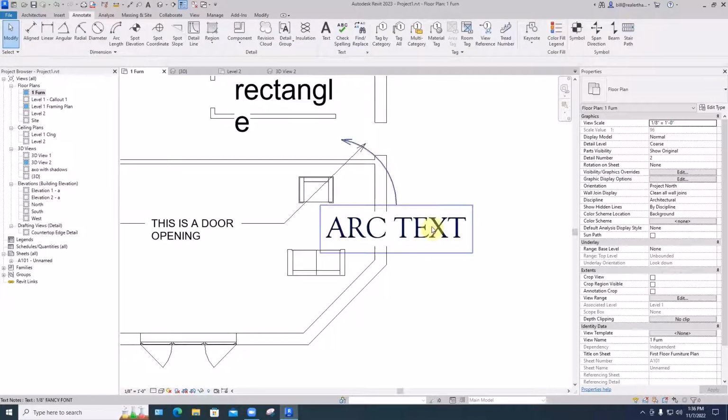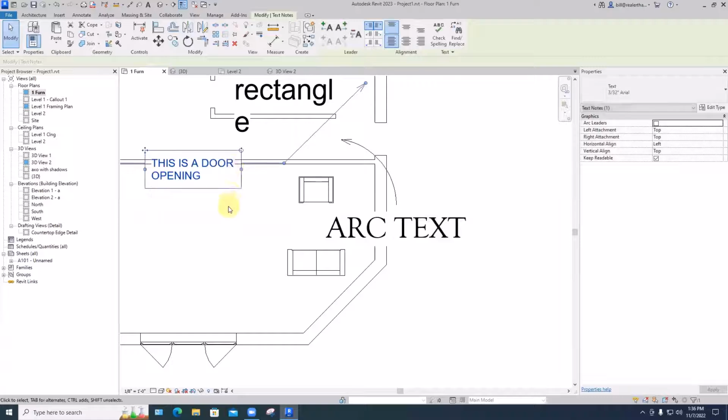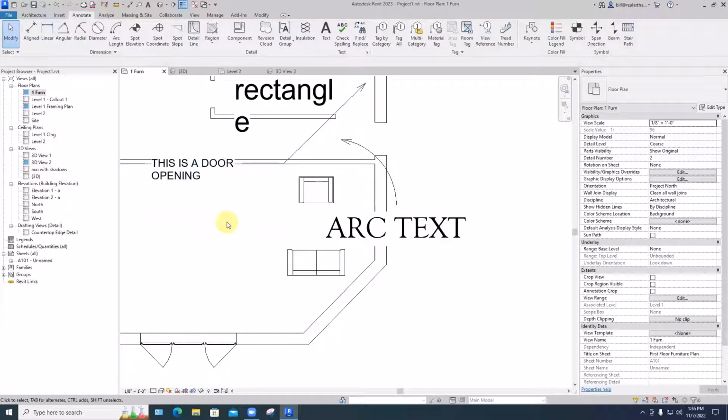You'll notice that this style of text, let's see about this one. These are both set to have an opaque background that will hide whatever's underneath them. And part of the reason for that is in a set of construction documents, whatever you've written, any notes or comments or specs or dimensions that are written have legal precedent over anything that's drawn.